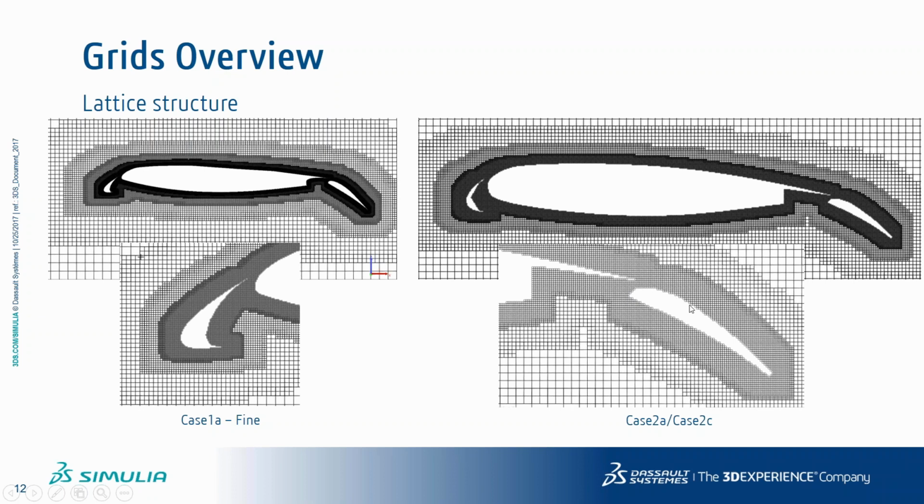You can see it's like a step-like pattern, but remember the previous slide I've shown you, every square near the wall can see up to 27 points on the wall. So in reality, this step-like pattern is not actually happening inside the solver, okay? It's just the points in the space where you know velocity, pressures, and so on. But the discretization of the profile of this wing is actually at a much higher order in the underlying iterations of the solver, okay? So don't be tricked by this aspect. It looks like it's a bit rough, but it isn't.